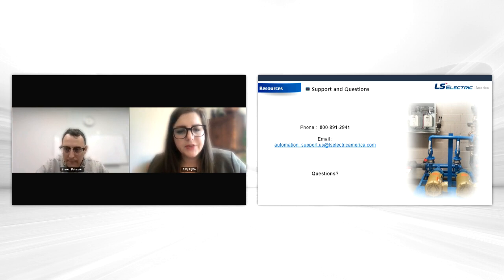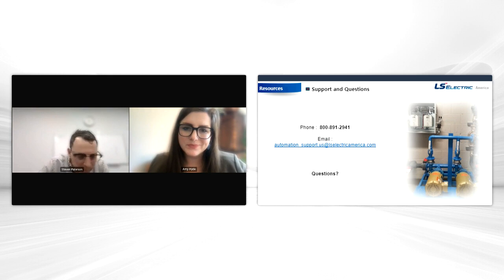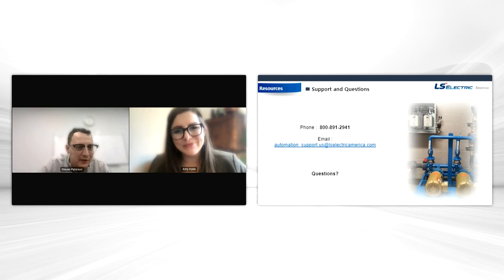One of the questions says, are there any parameters in the VFD to prevent the lag pump from short cycling? Yeah, I think that might have come up in the slide. We have some new features, the stabilization related parameters, and they're literally dedicated to preventing the lag pump from short cycling, because sometimes the lag pump comes on and then you hit a higher feedback and then it shuts down. There are three functions in there, the special lag stabilization parameters, that should help on that. It's good you asked that, because it's a new feature we added.